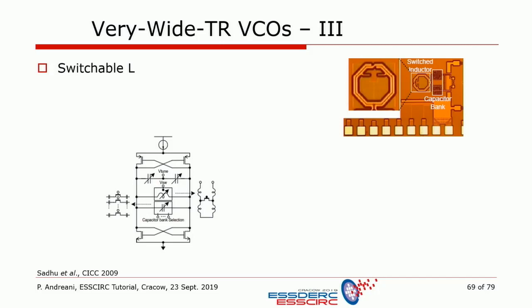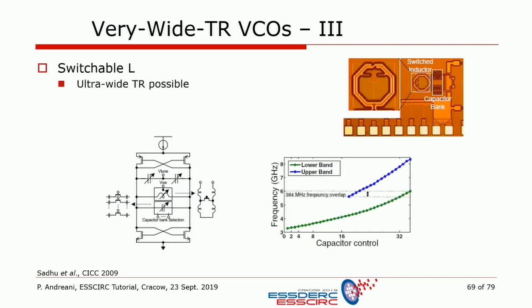Otherwise, why not switching the inductance? I mean, on the other hand, from the mathematical point of view, capacitance and inductance are really on the same footing. Okay? So people have done that. I mean, they've tried to switch the inductance, okay? And they've shown actually that ultra-wide tuning range are possible. But it turns out, at least so far, that to really have a low phase noise at a good figure of merit is difficult. Okay? It is difficult.